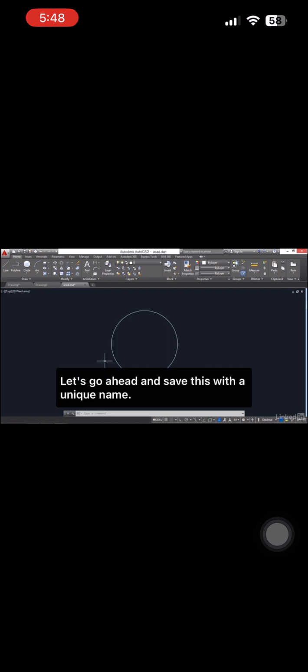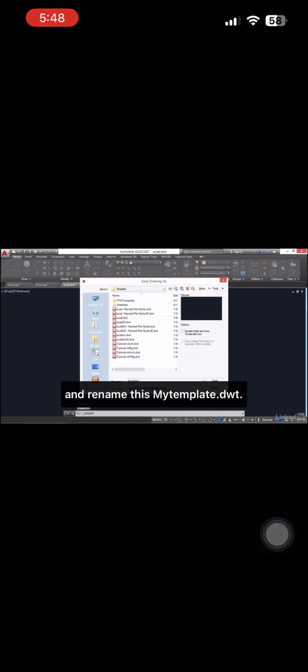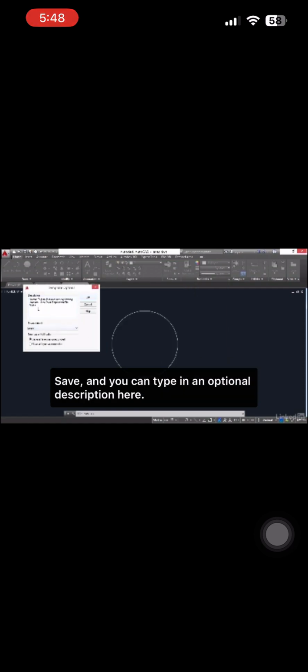Let's go ahead and save this with a unique name. So click Save As and rename this My Template.dwt. Save, and you can type in an optional description here.